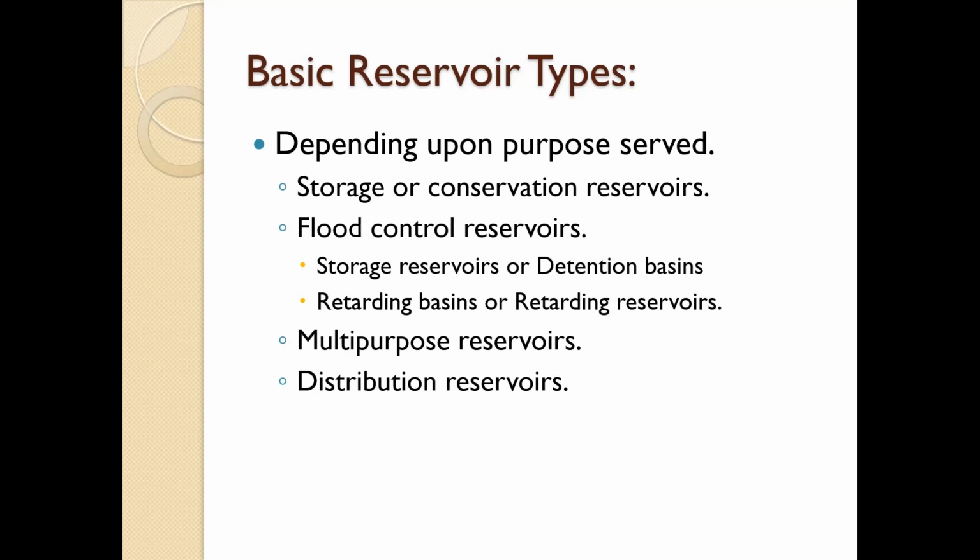Incidentally, in addition to conserving water for later use, the storage of floodwaters may also reduce flood damage below the reservoir. Hence, a reservoir can be used for controlling floods either solely or in addition to other purposes. In the former case, it is known as a flood control reservoir or a single purpose flood control reservoir, and in the latter case it is called a multi-purpose reservoir.